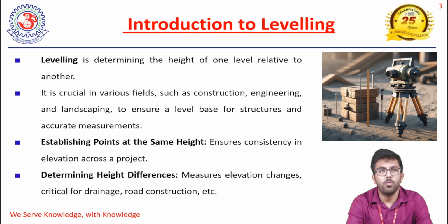Now, what is the purpose of leveling? There are basically two purposes of leveling: establishing points at the same height and also determining the height difference. So establishing points at the same height ensures a consistency in elevation across the project. Like when with respect to a known point, we are establishing the other points. So we know that the point B, C, D, E, for example, is at what level compared to point A.